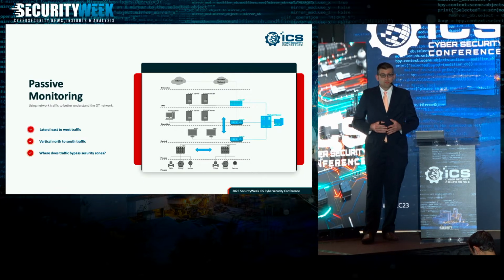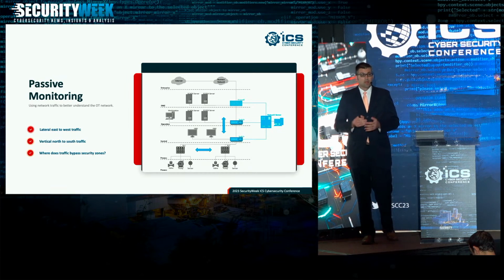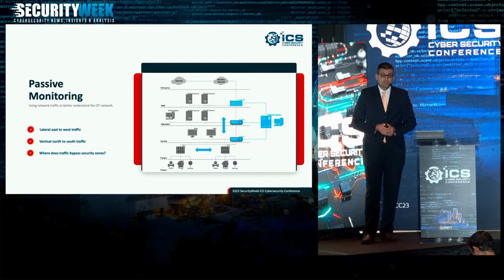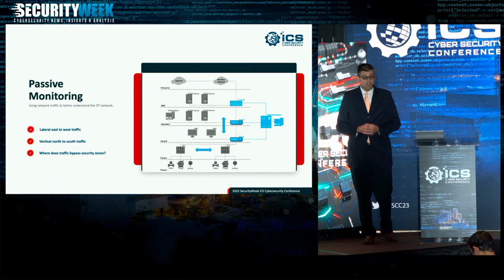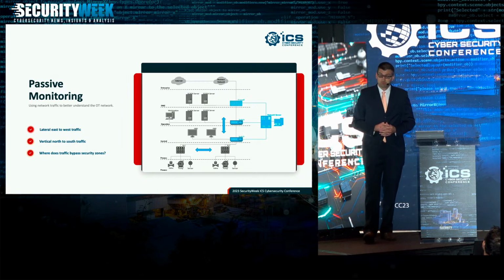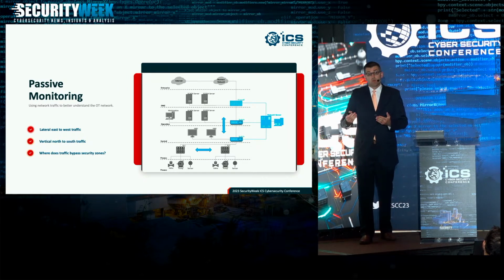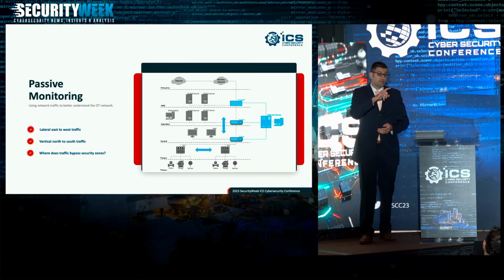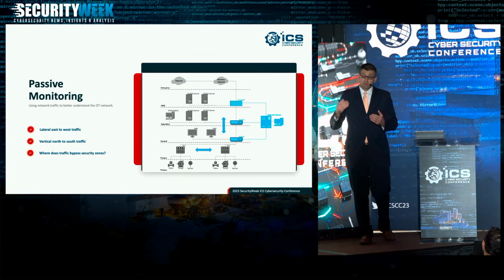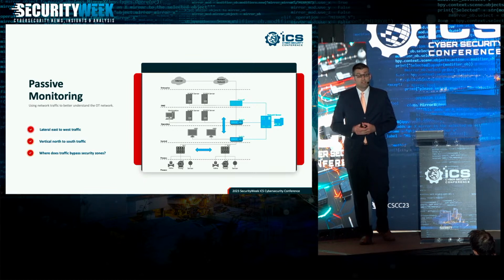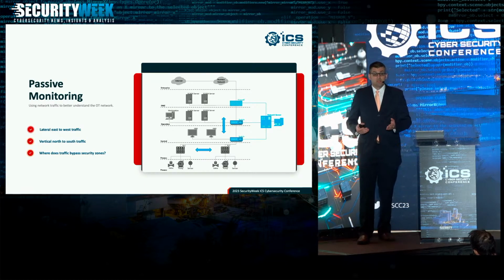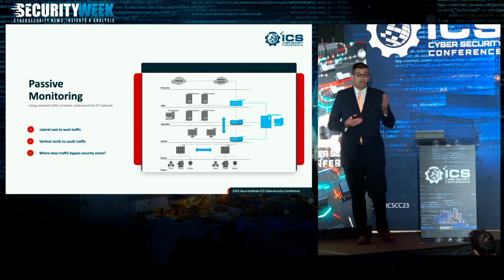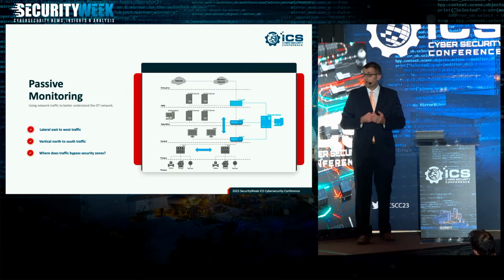And then the last one we saw was really the worrisome one, probably kind of the scary one. I got a call, and hey, did you know you're actually getting scans from an IP address that traces back to a country that's known for cyber attacks? No, I did not. So we actually saw where there was a country again known for cyber attacks, and they were doing scans to a PLC buried very deep within our control system. We actually went through the full incident response, found out that it was just a scan, never actually made a successful connection, but it was still something we didn't know about until we got passive monitoring in and discovered that device is out there, and this is the communication that's happening between it and everything else.